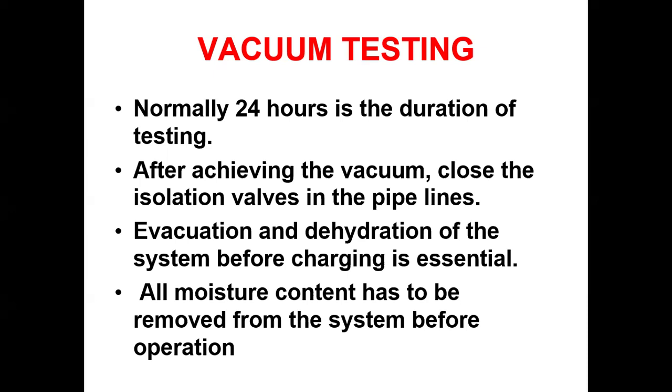Generally this vacuum testing is done at the outdoor unit, not at the intermediate pipe connections. It should be done right on the ODU itself. On the ODU side, you have the charging port. On the charging port, you do this vacuuming.